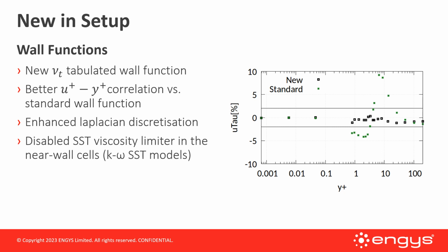Wall functions are used to avoid resolving the boundary layer all the way down to the viscous sublayer. In the k-omega SST turbulence model, a Y plus insensitive wall function is used in theory for omega and turbulent production, and a zero Neumann condition is used for k. The issue is that the inherited wall functions from OpenFOAM present strong variations in the computed shear stress depending on